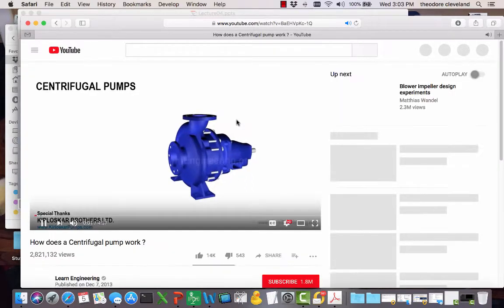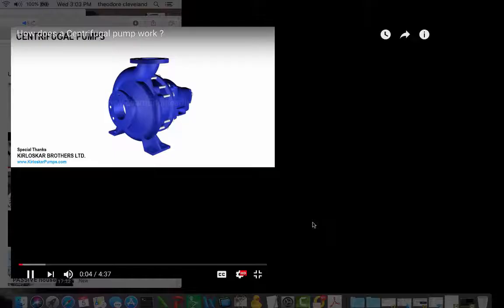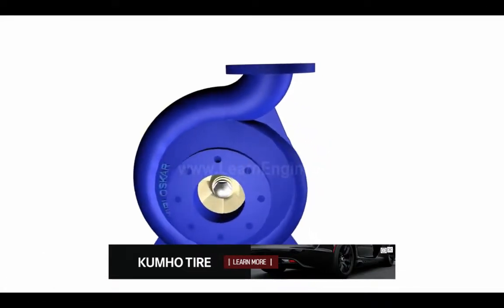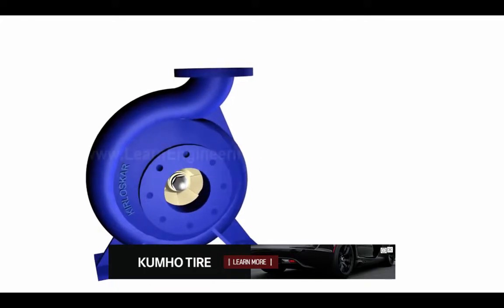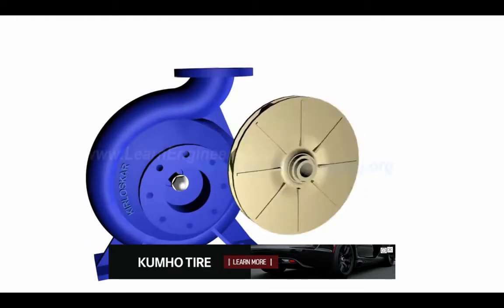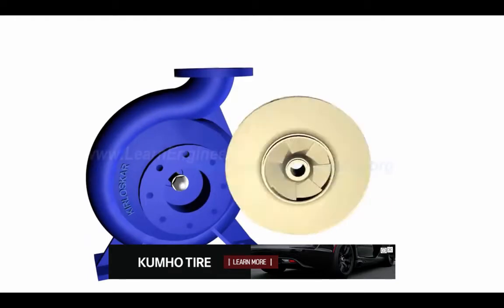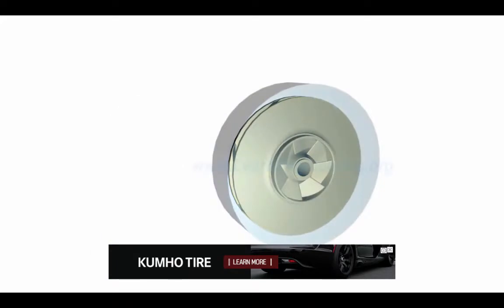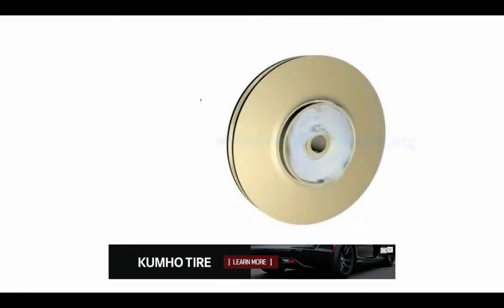Centrifugal pumps are the most preferred pumping devices in the hydraulic world. In this video, we will have a conceptual overview of working of centrifugal pumps. At the heart of the system lies the impeller. It has got a series of curved vanes fitted inside shroud plates. The impeller is always immersed in water. When the impeller is made to rotate, it makes the fluid surrounding it also rotate.